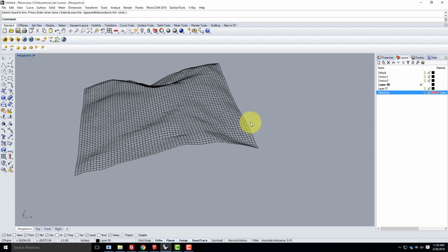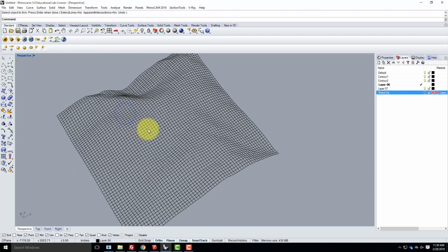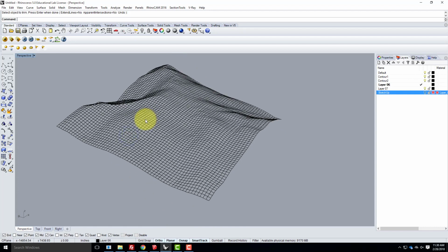So once I get to this point, now's your opportunity to make sure you save your file. And I don't say that lightly, because the curve network is challenging. It's going to be slow on the computer. It's going to take a little while. You want to make sure you save it. In the old days, it used to crash the computers more than half the time when you try to do it. Now you have a pretty likely shot that it's going to work.